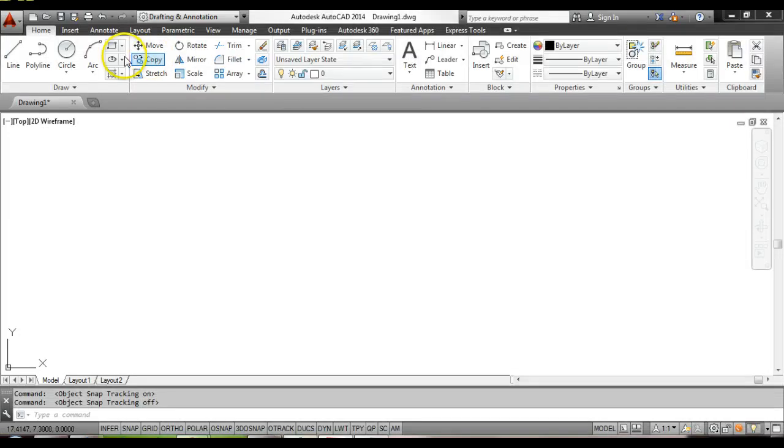Inside of these icons, you also have some flyouts. If you click to the right of some of these icons, you'll see that rectangle and polygon are very similar type commands, so they've grouped them together in one icon. Same thing here. Those are different ways that you can draw ellipses. So they've put that all together using these drop-down boxes.